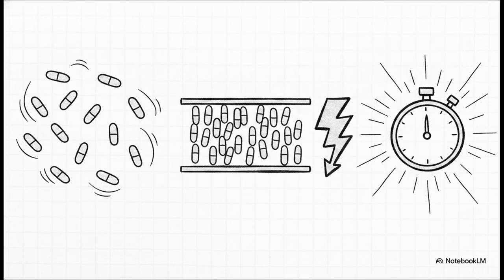Okay, here is exactly how you get full marks on this. Your examiner is looking for 3 specific keywords. First, you need to state that the molecules are aligned but free to move, meaning they have directional order but lack strict positional order. Second, explicitly mention that this unique state allows their orientation to easily change under an electric field. And finally, tie it all together by concluding that this results in a fast response time, which is absolutely critical for the rapid pixel switching needed in modern displays. Hit those 3 points and you've nailed it.